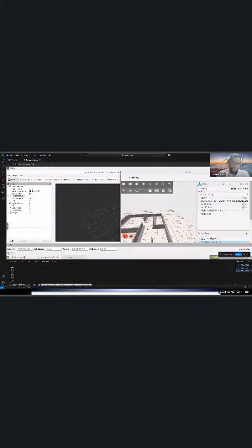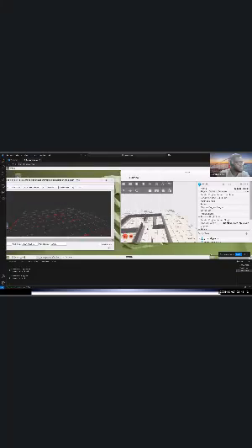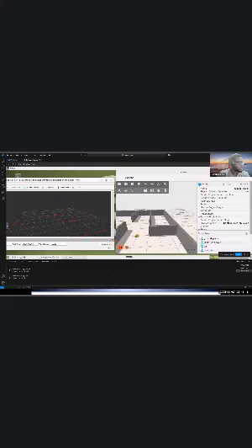So if I run this, now you see that the robot is gonna move. So let me try zooming in. So you see the LiDAR scan. Let me try minimizing this so we can also see this side by side. Like this, we're able to echo the scan topic. So if I move, you see that the robot moves. Because the speed is low, we're going to increase the speed by, let's say, 0.1. So let's use W. We do that, then the robot moves.